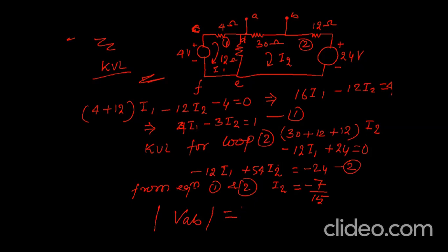it will be equal to this 7 by 15 multiplied by 30 ohm resistance. So it will be 14 volt. So this is VTH. So VTH is known, and that is equal to the VAB. So now we have almost solved whatever we needed.